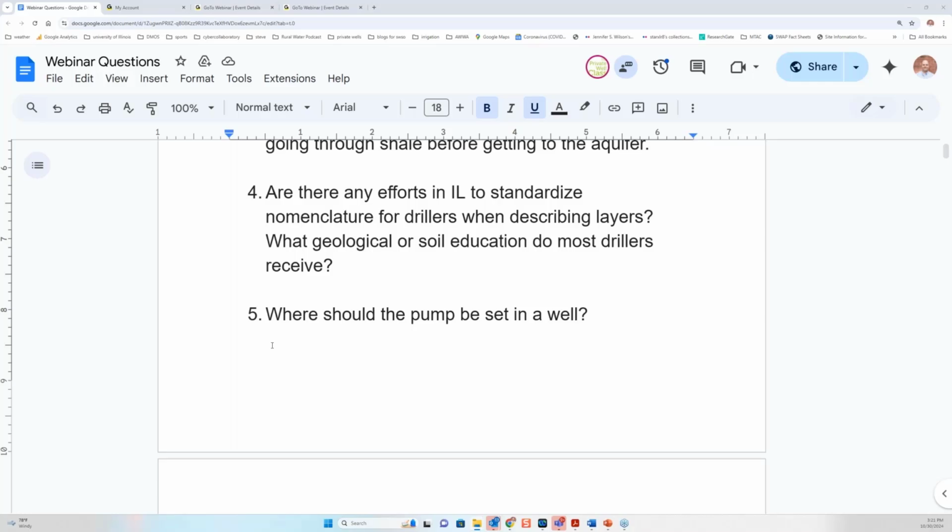Like a shale that's not going to have a lot of stuff slough off over time, so that you have less dissolved solids or total solids being taken up by the pump. That's my way to answer that. A driller may have a different view or be able to provide a lot more detail. But in the end, it really depends on all the factors: geology, water level, screen, location, all that.